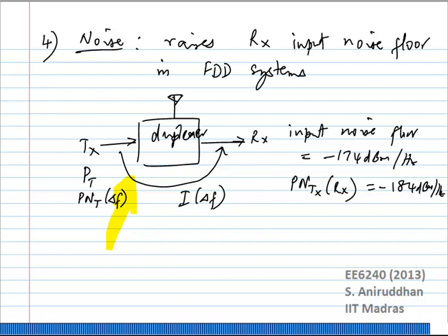Okay, so that is as far as transmitters are concerned. Any questions? There is really not a lot of detailed analysis we can do, because the transmitter in general is much simpler than the receiver. Really, in most cases you would end up using a direct conversion transmitter. You would have a baseband filter, an upconversion mixer.